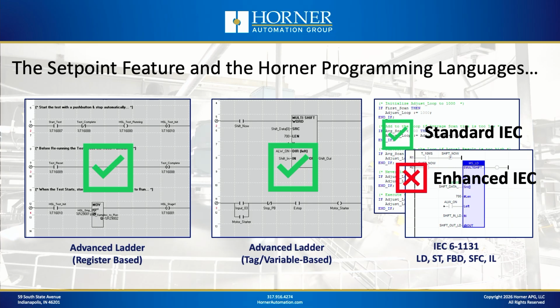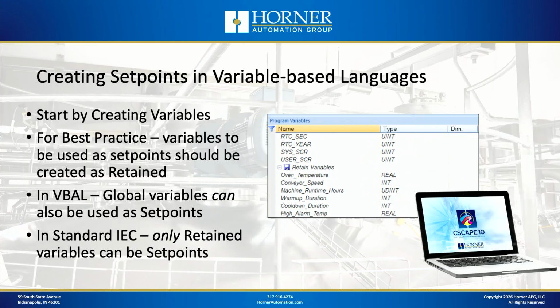Horner has a variety of different languages that are all available in Cscape. We have advanced ladder that's register-based, advanced ladder that is variable-based, which is the more modern approach to American-style ladder. Of course, we offer IEC as well with our standard IEC and then what we call enhanced IEC. Now, the Setpoint table feature is available in all these languages except enhanced IEC. So keep that in mind.